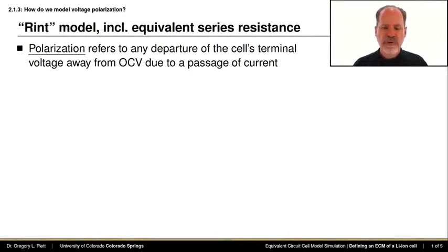So far this week, you've learned how to create an equivalent circuit model of a battery cell that includes open circuit voltage that is dependent on a cell state of charge. In this lesson, you will learn how to add elements to this model that describe voltage polarization.